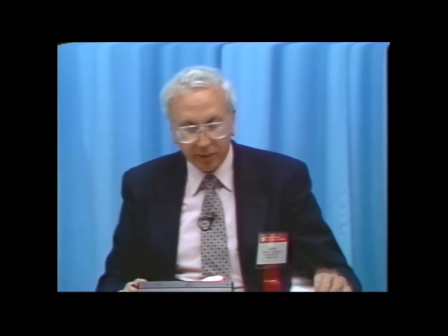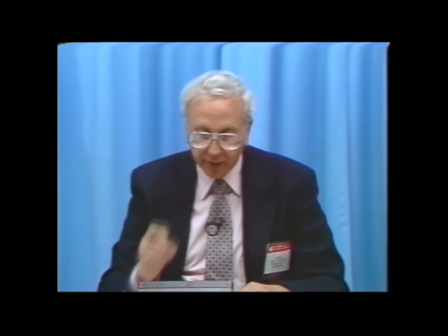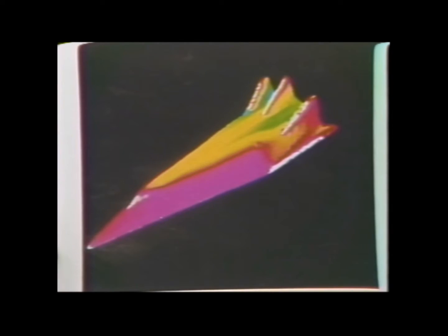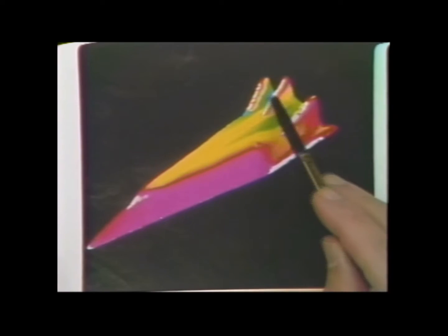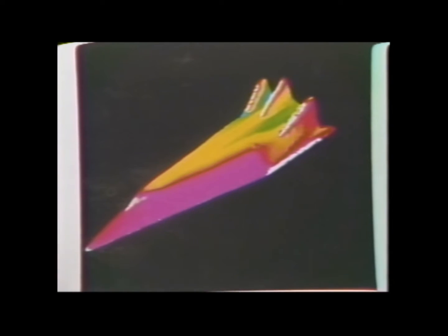Let's look at some other data. These data are not in your book, but I have to show them to you anyway. Here is a color graphic showing the surface pressure distribution over the X-24 as calculated from these Navier-Stokes calculations, showing what you would expect. A relatively constant pressure along the side of the X-24, peaks in pressure in the nose region and the canopy region, along the leading edges of the tail and the leading edges of the wing. Typical kind of pressure distribution.